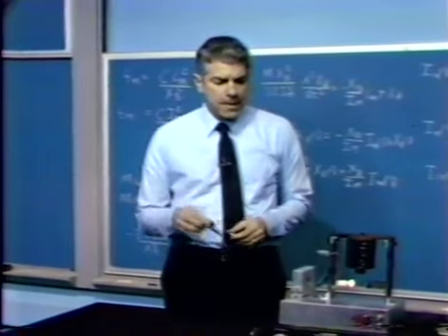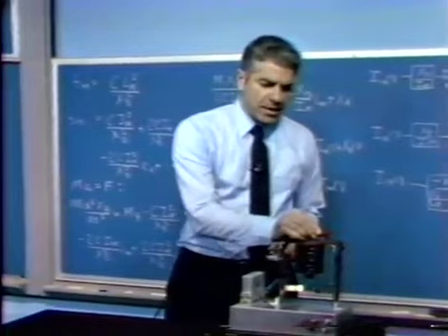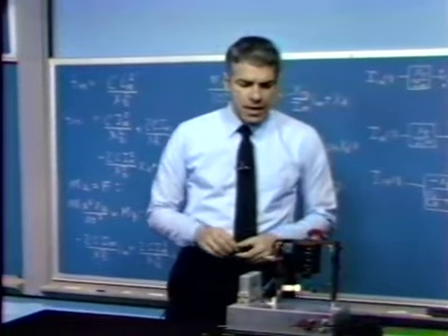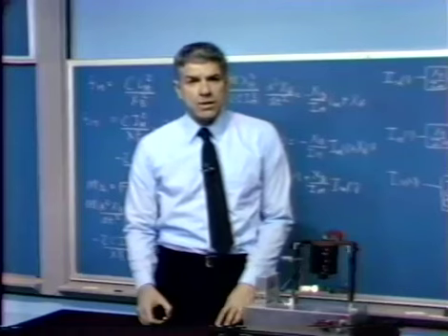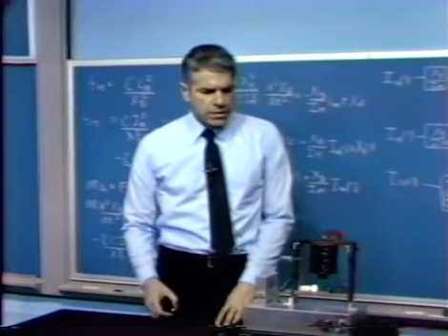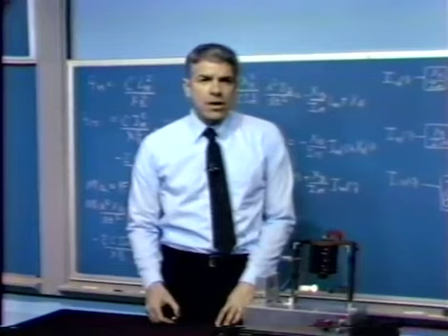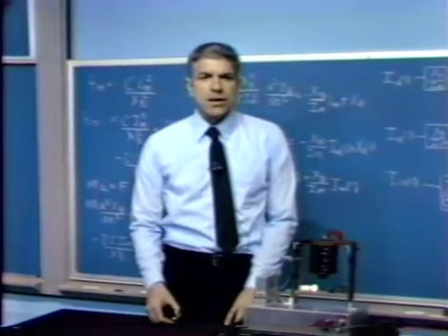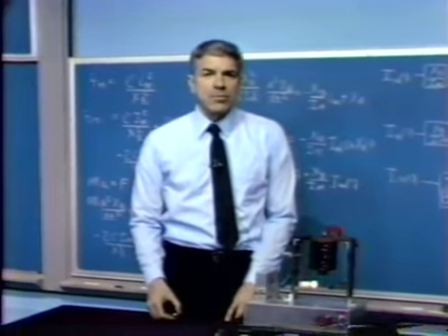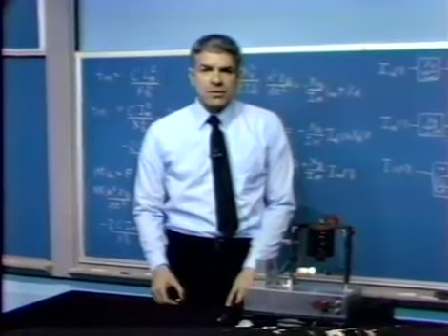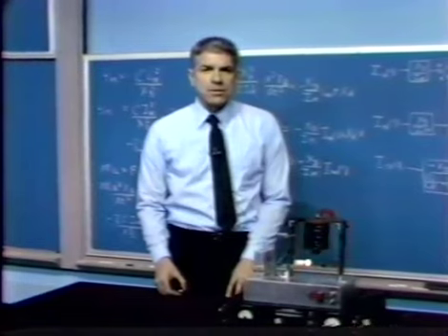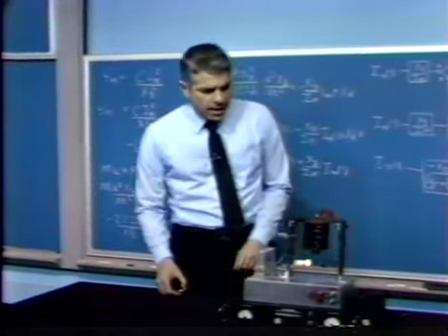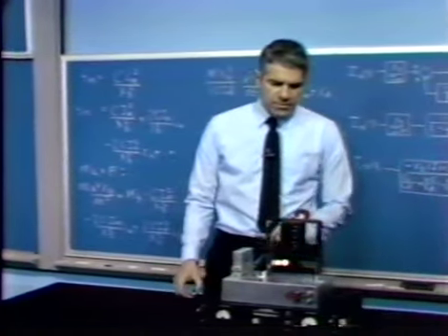But there's a way to win this game, and in fact it's used in, for example, the suspension of aircraft models in the MIT wind tunnel. What one does is build a system where you control the strength of a magnetic field. You measure ball position and then adjust the strength of the magnetic field in order to keep the ball a prescribed distance from the magnet. And this system in front of me does this.